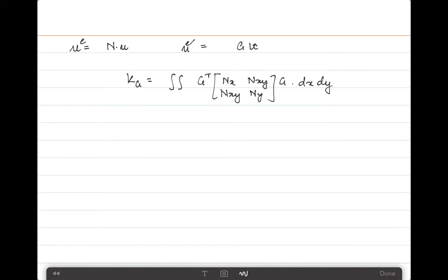If the element is of course of an isoparametric family, then you can make it into the generalized coordinates psi and eta. You need to get a Jacobian matrix in that case, and your limits move from x, y to psi and eta.